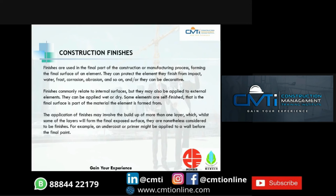Next, finishes commonly relate to internal surfaces, but they can also be applied to external elements. They can be applied wet or dry. Some elements are self-finished, that is, the final surface is part of the material the element is formed from. Next, the application of finishes may involve the buildup of more than one layer, which, while some of the layers will form the final exposed surface, they are nonetheless considered to be finishes. For example, an undercoat or primer might be applied to a wall before the final paint.